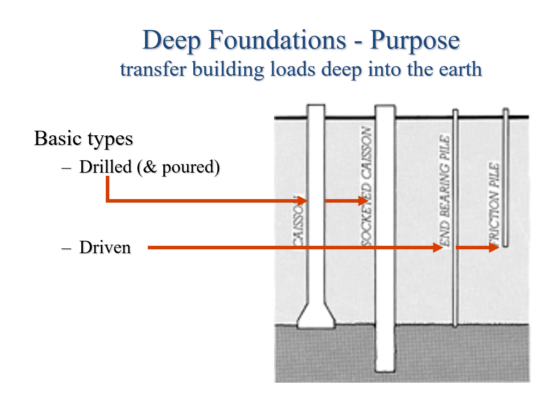But the obvious difference in a socket caisson is that it's been drilled. You've drilled into the rock, and you're actually pinning, like driving a pin or a nail into a piece of wood. That caisson becomes part of the rock at the lower level. And one is an end-bearing pile, and the other is a friction pile. That's commonly used in pile driving. A lot of times it was wood in the old days. Now mostly you see I-beams being pile driven. Very quick. You don't have to wait for concrete to dry and cure. That's the reason they're becoming very popular once again.